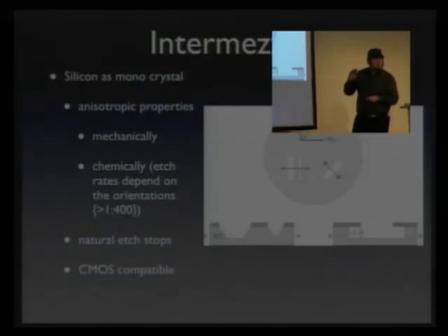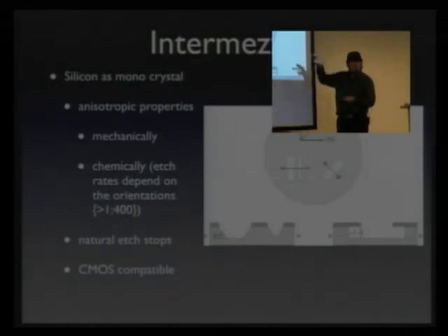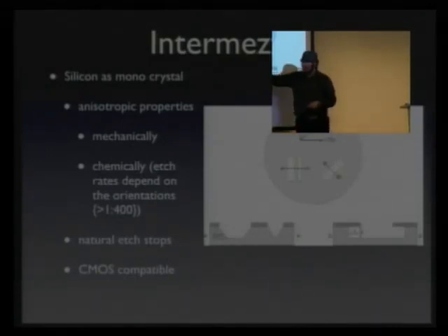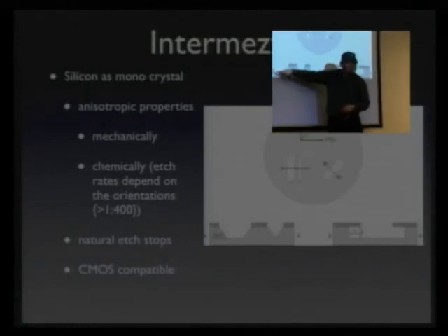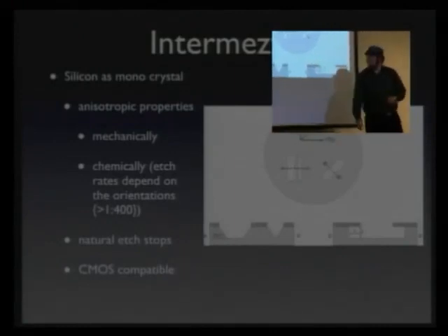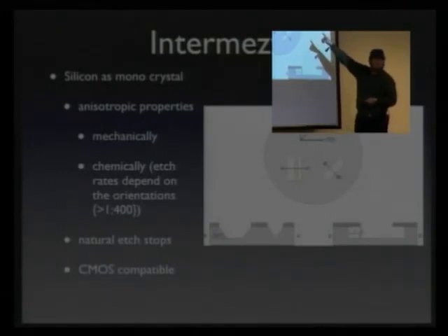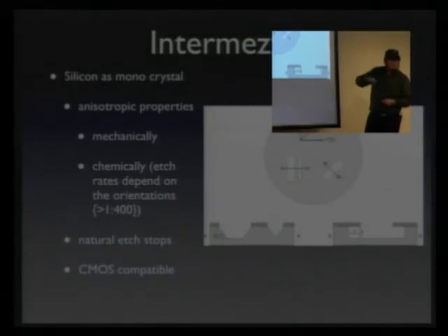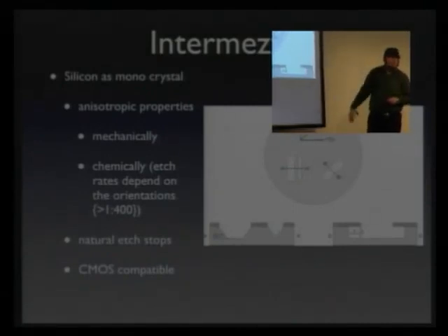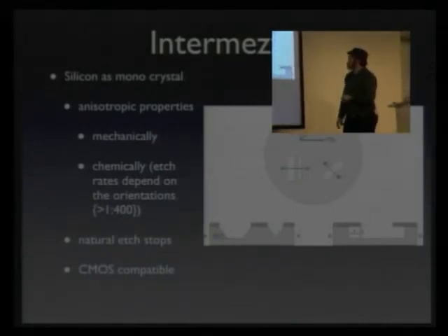This is really an almost engineered material, and so it etches differently in different directions because there are planes in the crystal, and it suddenly stops there when you etch something. This is why you get this strange appearance, and you will always get this angle here, which you normally don't have in other materials. And these are the planes you have in the crystal. But explaining this is a 3-hour lecture, so I don't want to bore you any further with this.